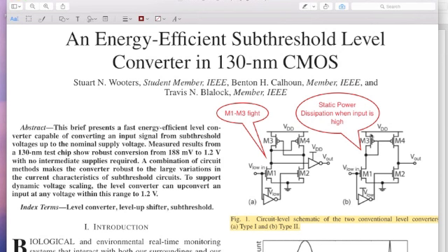So the idea here is that this PMOS gate is not tied to ground. Let us see what happens here. When input is 0, M1 is off, M2 is on, and say the output is low out here, and when M1 is off, this node rises up to VDD, so M4 is also off essentially.